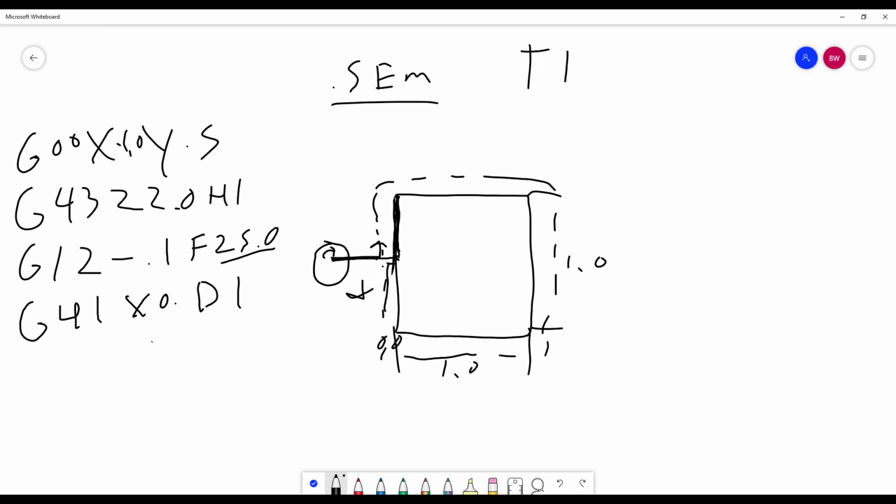Now the cutter, and I'll clean this up quickly, is going to move, and I'll get rid of these 1 inch numbers. Remember that. The cutter is going to move to right here. And it's going to comp whatever value is in the D1 column. And remember, the D1 column is on diameter, so it automatically knows to only compensate for the radius. So now we're right here.